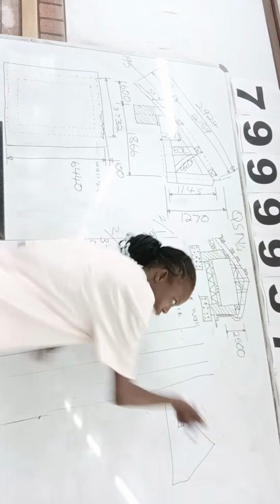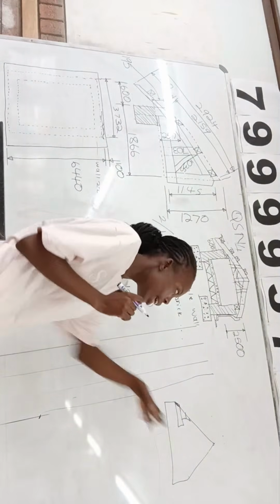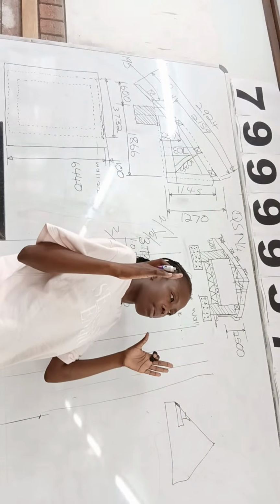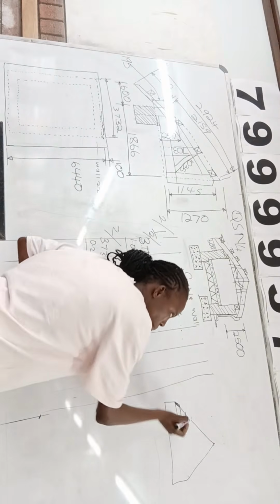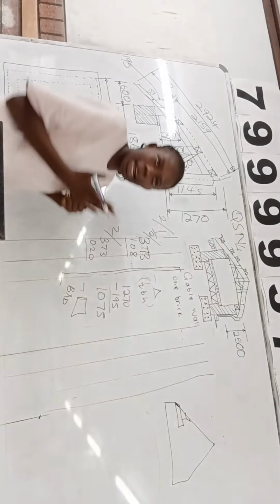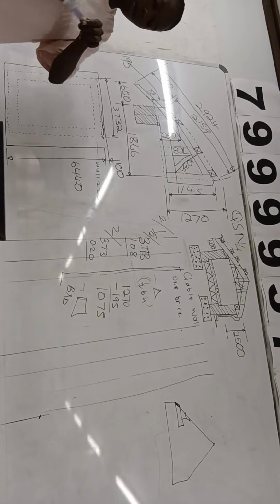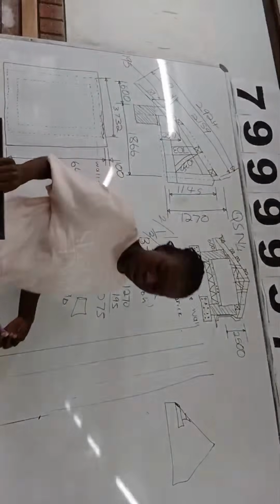So they will cut, especially this part, right? At the corners, they'll have to cut the bricks so that they will be able to fit here again. So a full brick will not be able to fit there. Even when you want to brick, like what I cut so that it will be able to align with that triangle again. So raking and cutting, we're talking about the cutting of bricks on the gable wall.